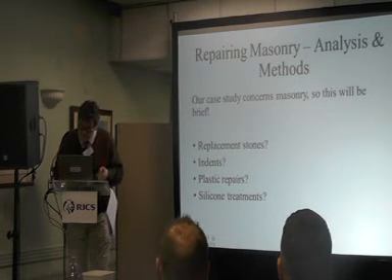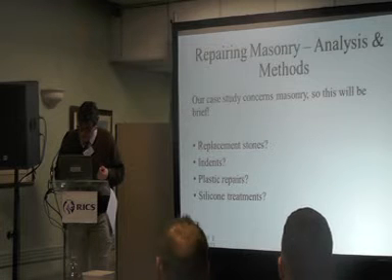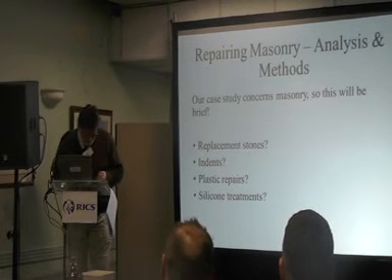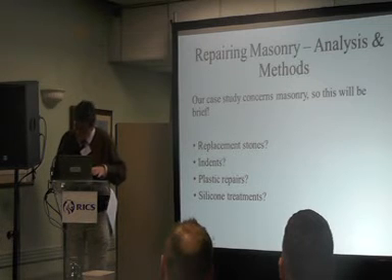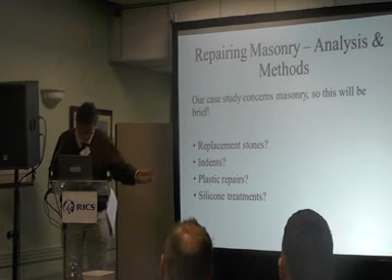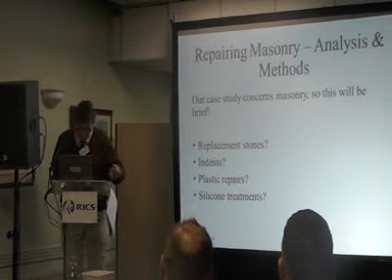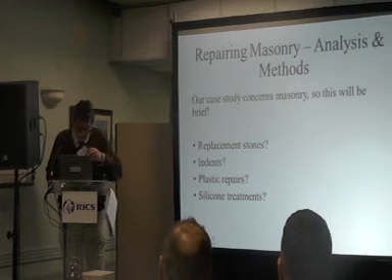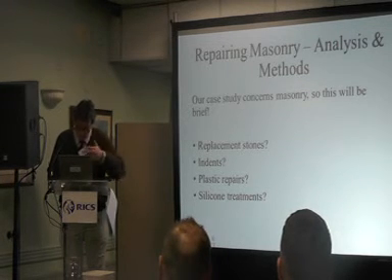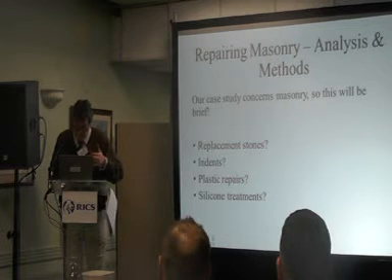Silicone treatments. Never. Never. Stone doesn't mind being wet. There's lots and lots of stones in the ground, in the sea, in rivers. It's wet in the environment. Stone doesn't break down just because it's wet. But if you try and prevent moisture from migrating through stone, the more porous the stone, the less long it's going to last.